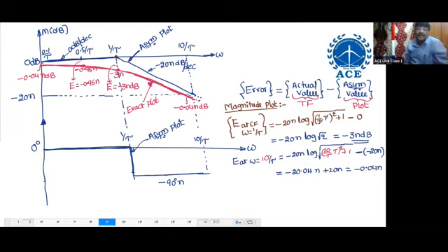Error is symmetrical about the corner frequency. Symmetrical means the error 1 decade below and 1 decade after is the same. At 0.5 by tau, half the frequency, and at double the frequency, the error is the same. Be sure to remember: the error is always symmetrical about the corner frequency, and the error is largest at the corner frequency. That's all. Next, errors in the phase plot.